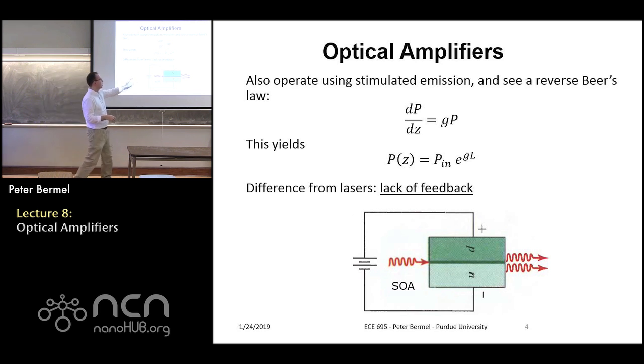So basically the idea is light comes in with a certain Pn, and comes out at Pn times e to the GL. The key thing here is that if you have many of these links, and every time you have a gain of e to the GL, that means you should have e to the GL equal to the loss along each of these links between individual amplifiers, right? In other words, this is going to maintain a kind of equilibrium.